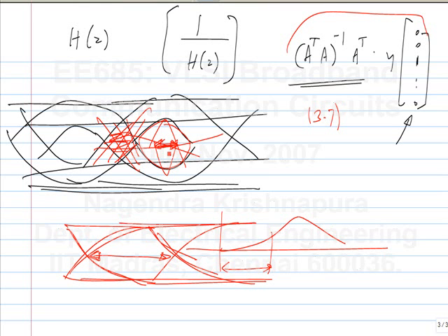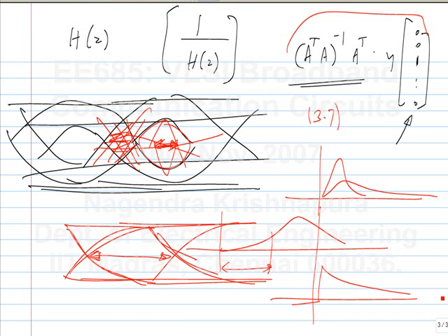No, that is because the pulse itself looks like that. See, the pulse goes from being maybe something like this to perhaps something like this. So the pulse itself has a longer tail on one side, right? Pulse response. So the same thing shows up in the eye diagram also. But if you do a single RC case, the response will be like this to a single pulse. And the eye diagram will look like this, which is also not symmetric in the horizontal direction.